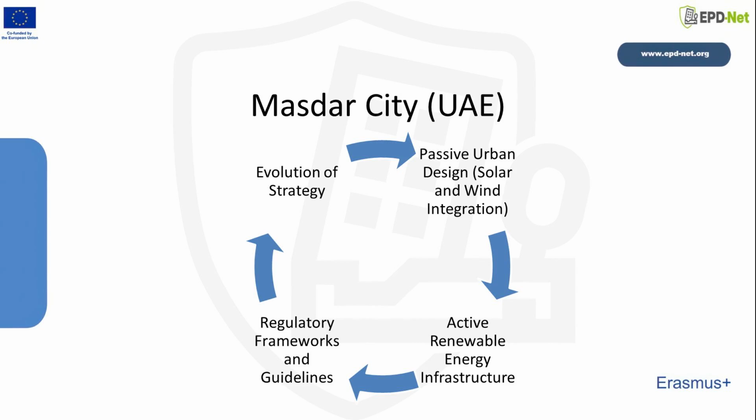Solar analysis, orientation and shading. Buildings are oriented to optimize natural daylight while simultaneously controlling solar heat gain to balance illumination with thermal efficiency. The city employs high-performance facades and shaded courtyards to minimize the need for mechanical cooling. Compact morphology: the city utilizes a high-density, low-rise structure to minimize urban sprawl and reduce energy consumption.